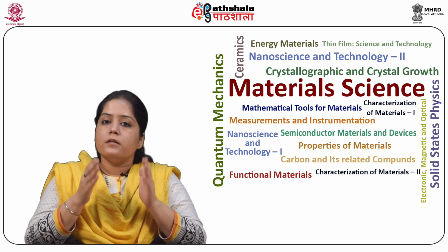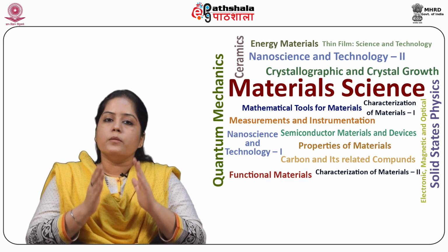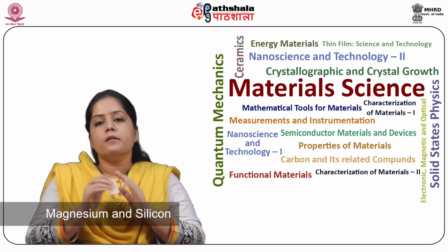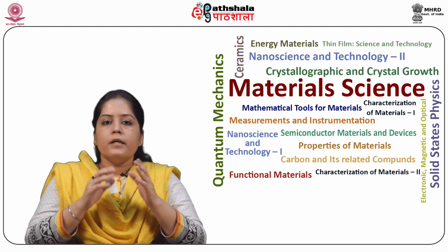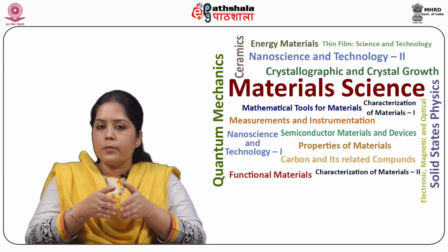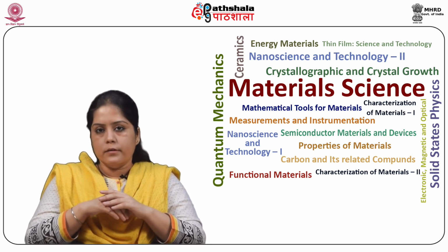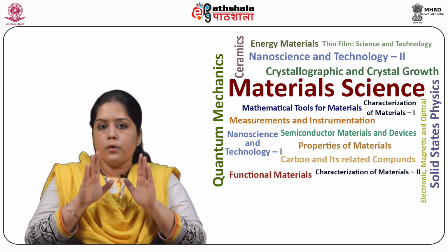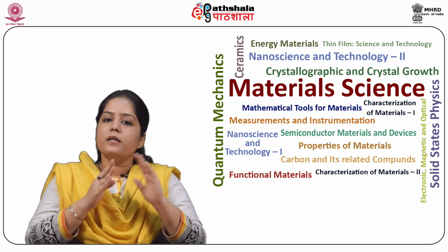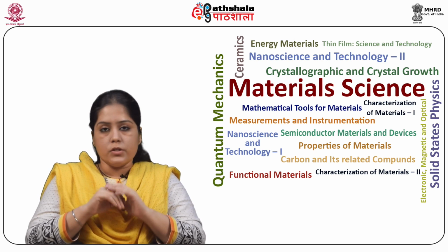And next, the 6000 series. They are alloyed with magnesium and silicon. They are easy to machine, they are weldable, and they can be precipitation hardened, but not to the high strengths that 2000 and 7000 can reach.